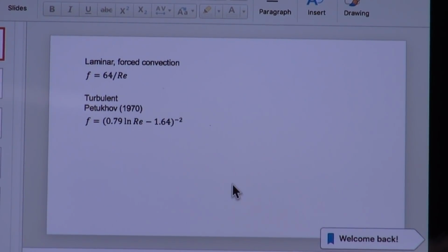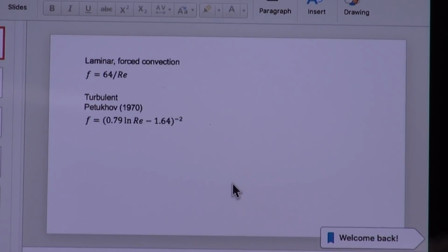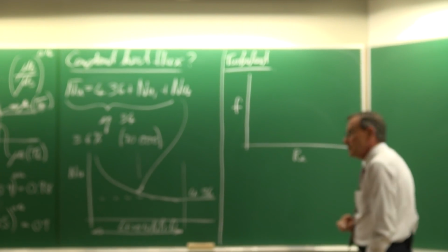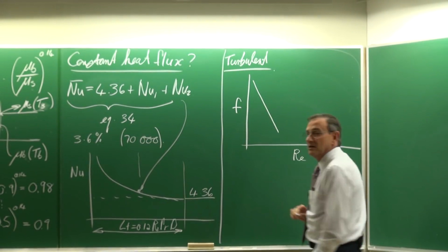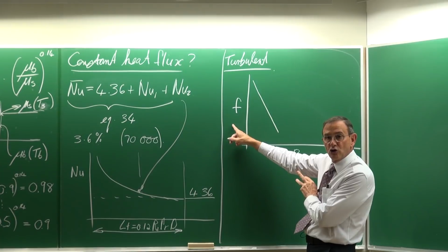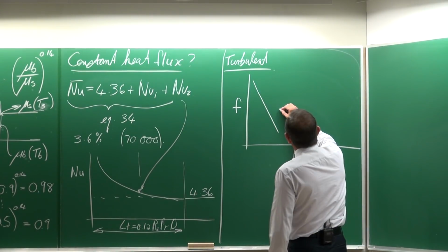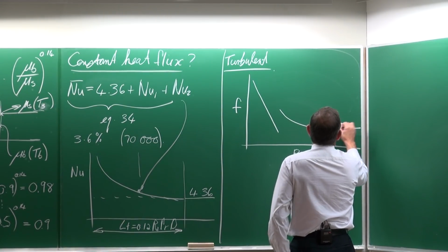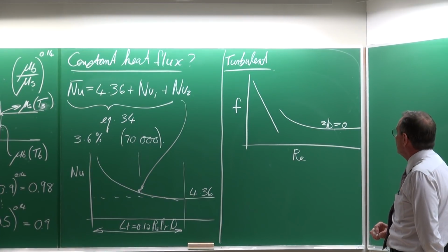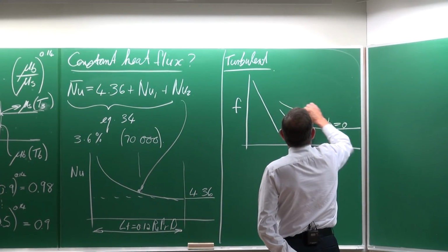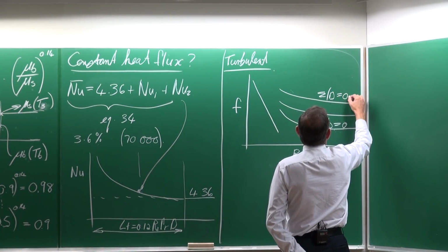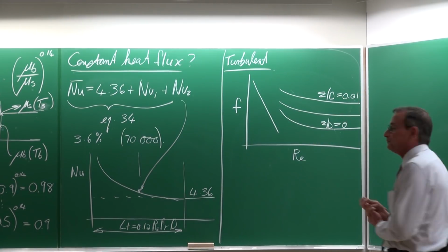With turbulent flow and with laminar flow, one of the very important things are the friction factor from the Moody chart. The friction factor, which is being given as a function of Reynolds number, and then you've got a straight line like that. However, take note, it's a log-log scale. Okay. And then we've got the transition area, and then we've got the line of which epsilon divided by d is equal to 0, so that's the smooth tube, and then you get the results for the rough tube. So maybe there's epsilon over d of 0.01 or something like that.